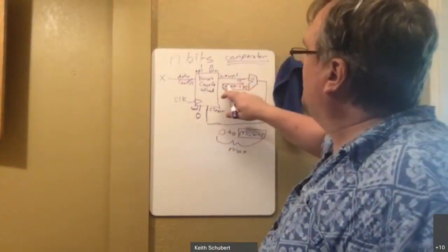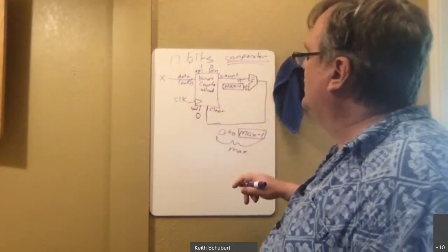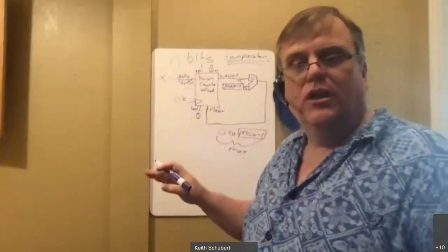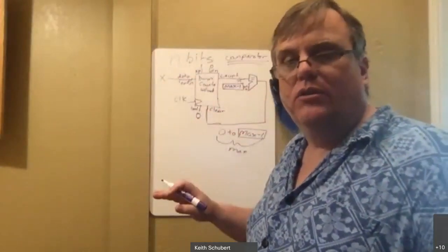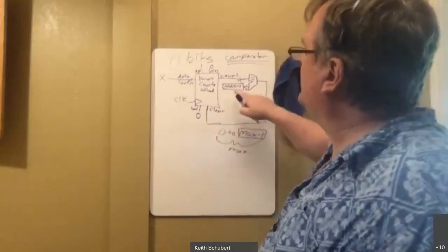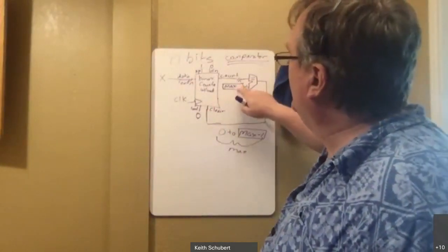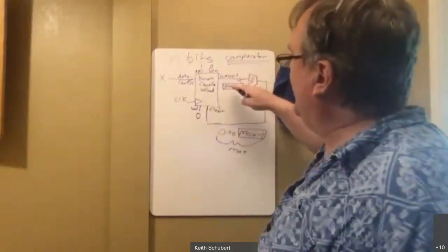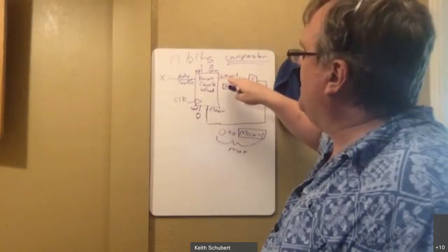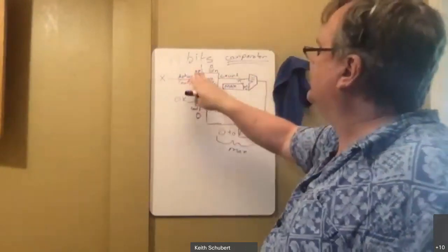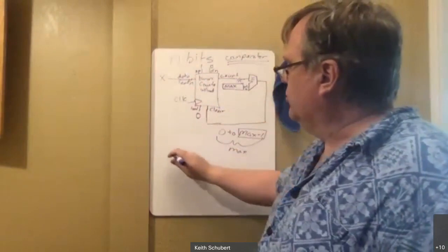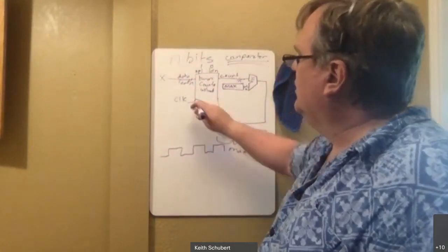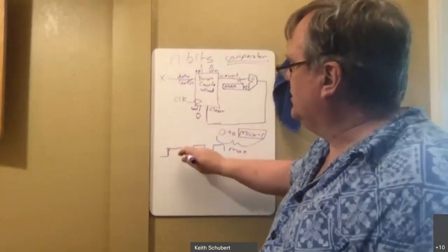So this is going to compare to max minus 1. And the second it hits max minus 1, it will instantly clear it. It won't wait for the next clock cycle. So what I have to do is, instead of comparing it to max minus 1, compare it to max. Because then the instant the count hits max, it will clear it and go to 0. So if you were looking at my clock pulses coming in, it doesn't have a bubble, so I'm measuring on the positive edge.